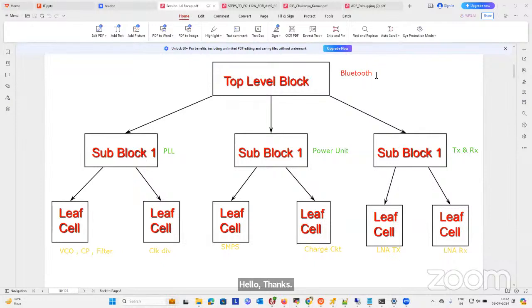So from the top level block, Bluetooth, we have split into sub blocks PLL, power unit, and TX and RX. And in the sub blocks, we have another split into the leaf level cells: VCO, charge pump, filter, clock divider, SMPS, charge circuit, LNA TX, and LNA RX. So this is how we break down the design and integrate it together to form a top level block.